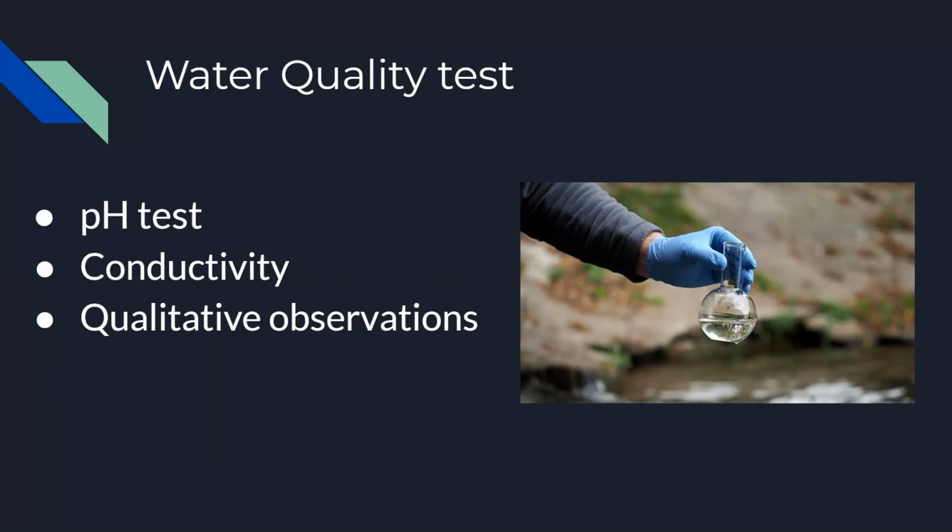Then lastly, we're going to be checking the quality observations of water. This means turbidity, clarity, taste, color, and odor of the water that are the dependent variables that we put in the project. Basically, matter suspended in the water absorbs light, making the water appear cloudy. This is called turbidity. Turbidity can be measured with several techniques. This shows the resistance of the transmission of light in water.